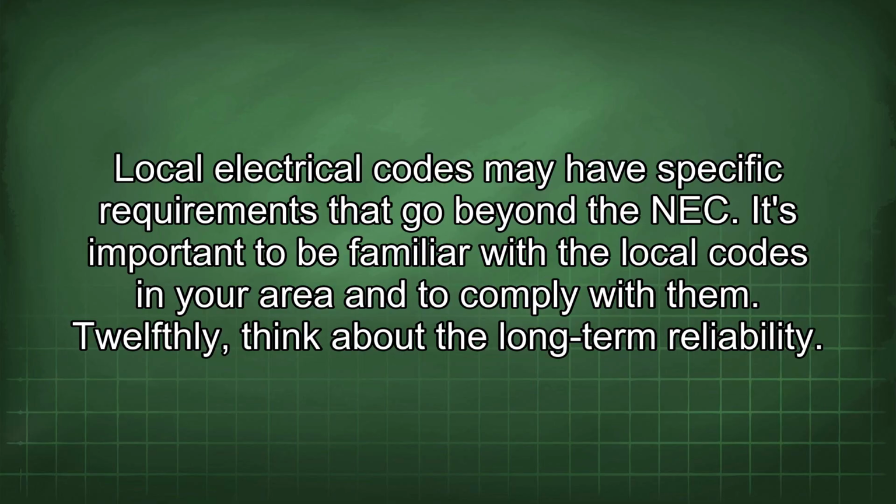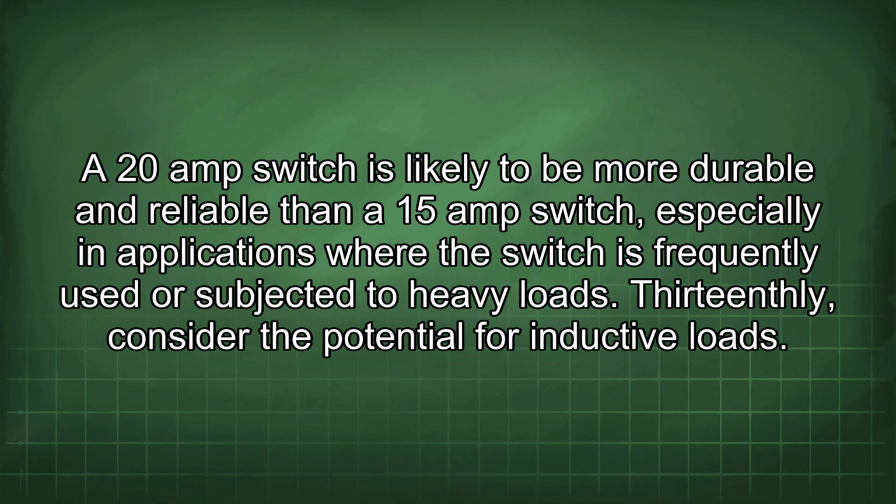12thly, think about the long-term reliability. A 20 amp switch is likely to be more durable and reliable than a 15 amp switch, especially in applications where the switch is frequently used or subjected to heavy loads.